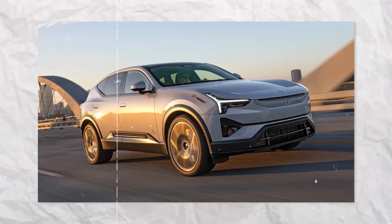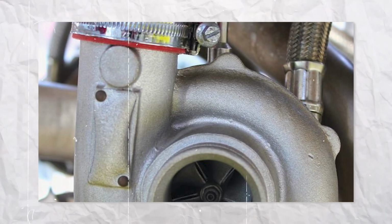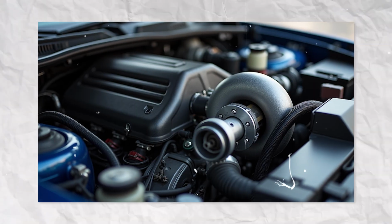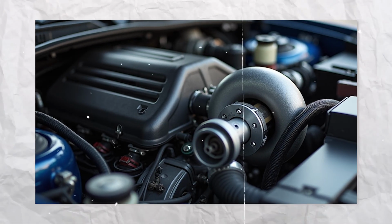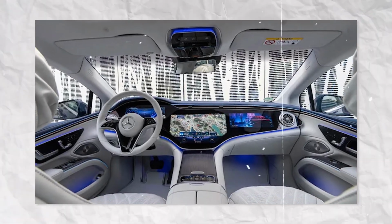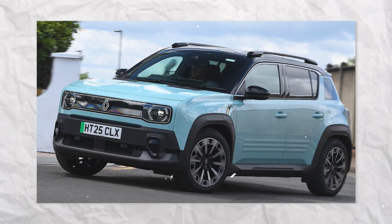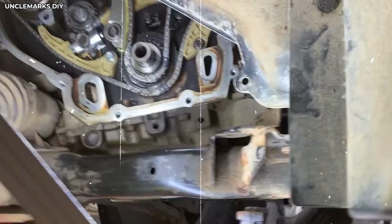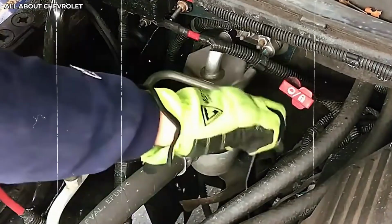If you typically only use 20 to 30% pedal travel during normal driving, the computer stretches that range. 50% pedal might only command 35% throttle opening because the ECU has learned you rarely need more than that. This creates what engineers call a softened throttle curve. Small pedal inputs produce even smaller throttle responses. You have to press significantly harder to get the same power output you'd get with factory calibration.